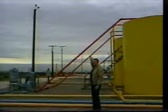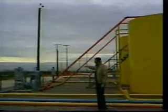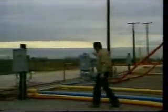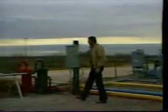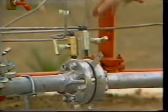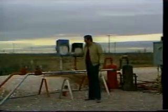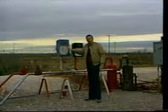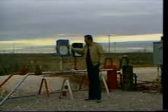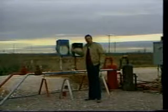Any vapor coming off the top of the oil is collected, compressed with this compressor behind me, and the clean gas from the separator and the gas coming off the top of the tanks then come through this meter, where with this orifice plate and these pressure taps we're able to record the pressures and the difference in pressures on this 1 week chart. With this chart, we're able to measure the volume that's passed through this line during a period of a week. The chart is changed weekly.